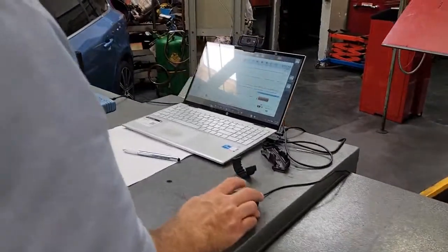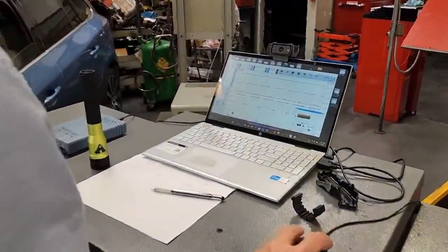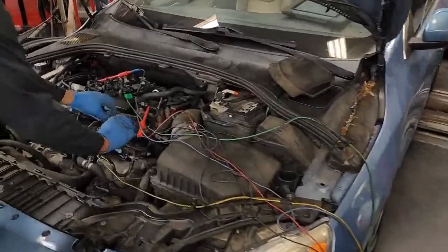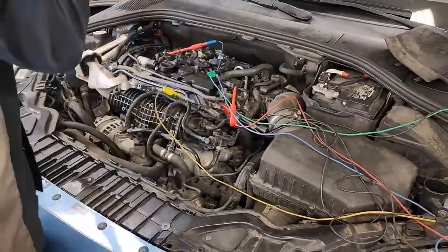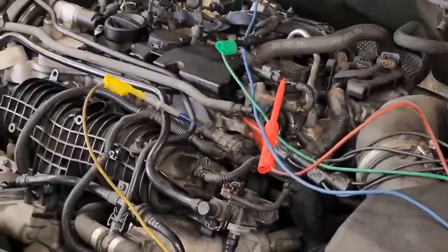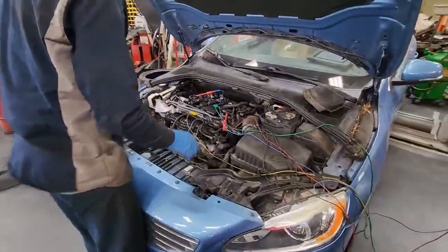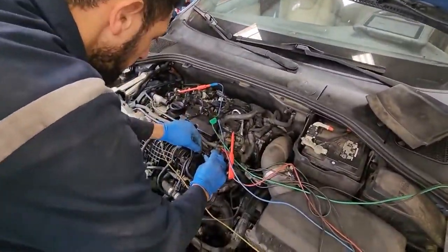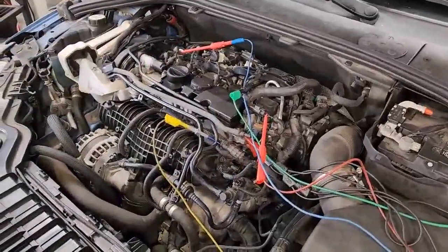Okay. So when it comes up and starts working, I will. So this is what a bad capture looks like, because it should be a square wave signal, and we were getting lots of, this is the oscilloscope monitoring the 3 wires. So like a ground, a 5-volt reference, and a sensor signal. So you could see the signals are all over the place. For example, this green line is from negative 1.9 volts to negative 3.3 volts.